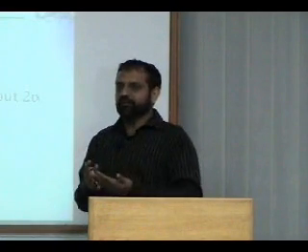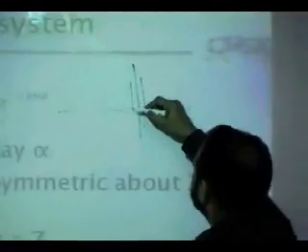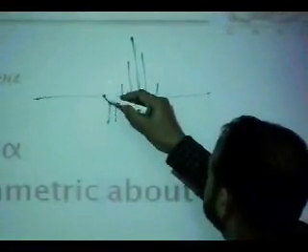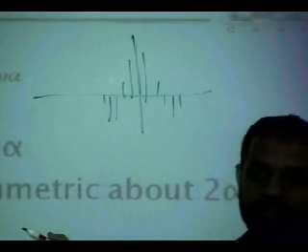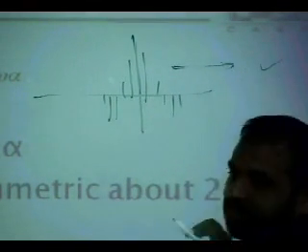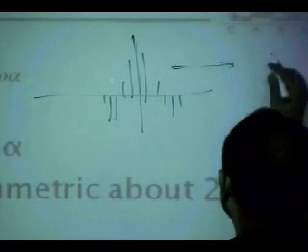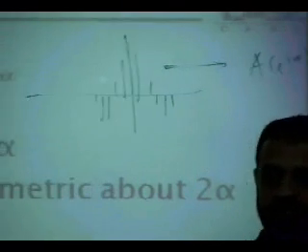And we have already learned what you need to do to make sure there is no phase distortion. You design a real and even sequence. Remember, a real and even sequence will have a real and even Fourier transform, meaning no phase in it. So a real and even sequence will have a real and even response, which will be all real. There will be no e to the j omega in it for sure.